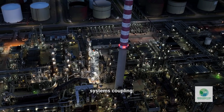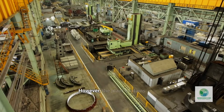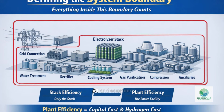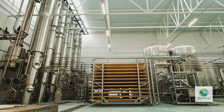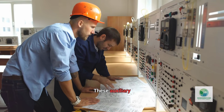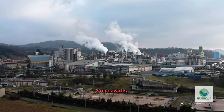Immediately we see the first system's coupling. Electrical inefficiency becomes thermal load. The plant must now manage this heat. However, the plant contains more than a stack and a rectifier. Return briefly to image number 1 and consider the balance of plant systems. Water treatment pumps, cooling pumps, control systems, instrumentation, and ventilation systems all consume electricity. These auxiliary loads typically represent 3 to 5% of stack power. In this example, we assume approximately 2 megawatts.